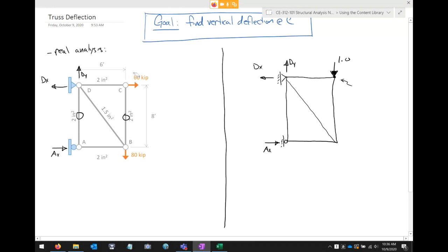In fact, you could also sort of look at this, make this a little easier. What is the force in member CD? 60 kips tension. Exactly right. See, so this isn't so bad. With some of these tools, you can knock this truss analysis out pretty easy. In fact, this member is AX in compression. Whatever AX is, we haven't figured that out yet.